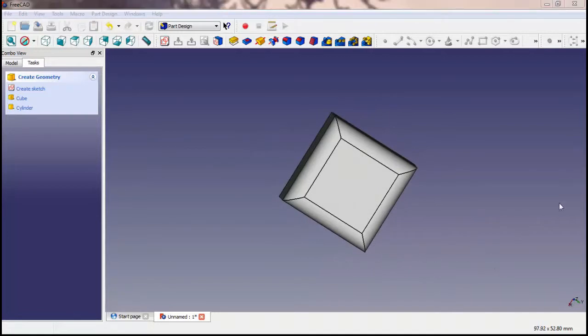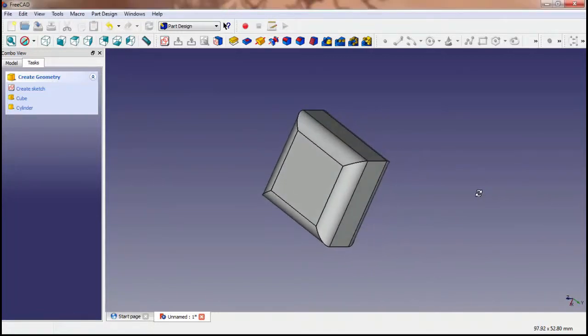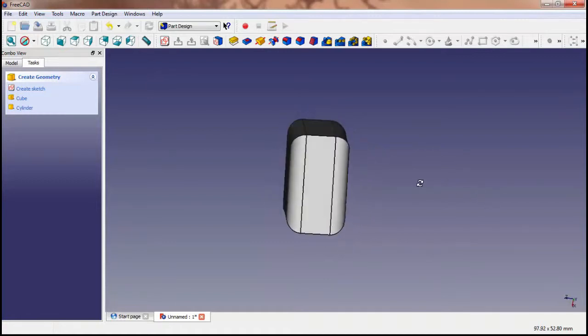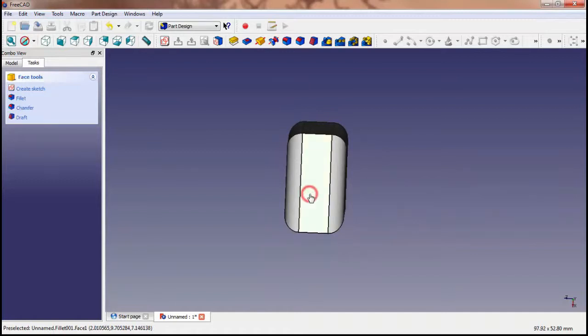The 3D object looks nice, but it's still useless for blocking webcam hackers. To make it useful, we will need to cut away the middle of our 3D object. To do this, we're going to draw the exact shape that we want to cut away. Select the flat surface on the short side of the 3D object and make sure that it's green.